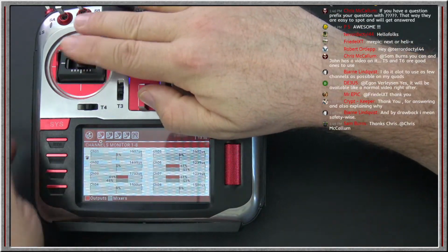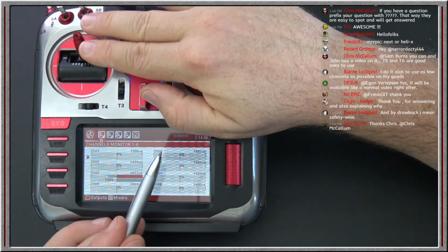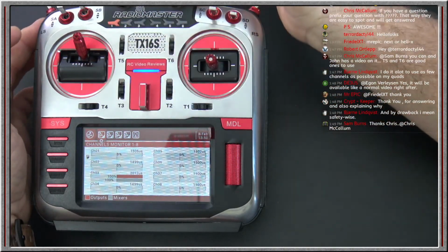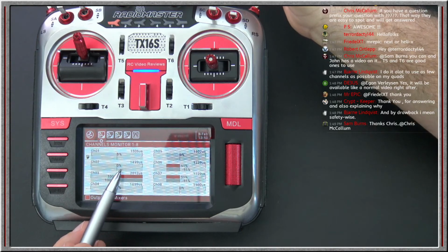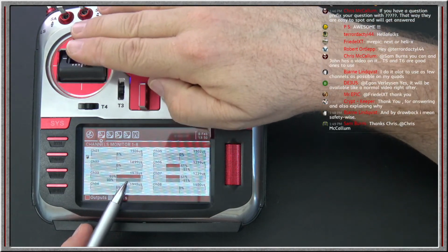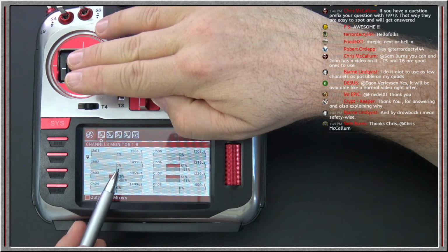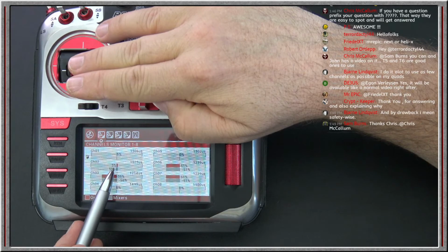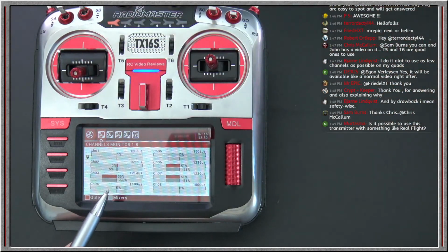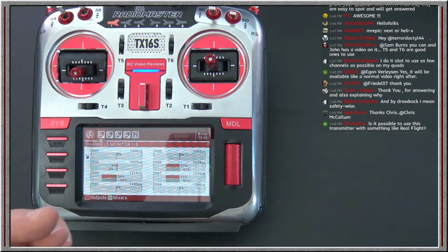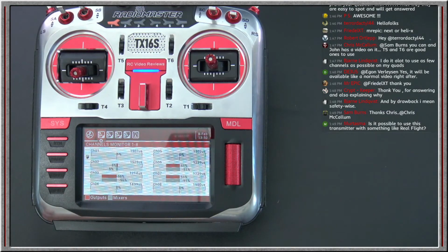So here, let's go back, reset everything. Flaps are up right now. Okay. Throttle's at 100%, and I'm going to bring the flaps down. Notice that there's no change to the elevator. Now, if I slow the plane down, slow it down, and I get down to about the 70% mark, watch the elevator. You see how it just kicked into that 5%? That's an example of using a logical switch for a mix. There are 100 different ways you could do that. So the answer to your question is you can absolutely use logical switches in your mixer. No problem.